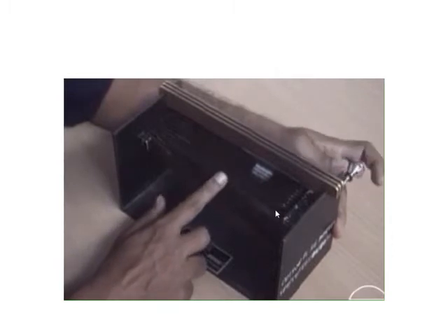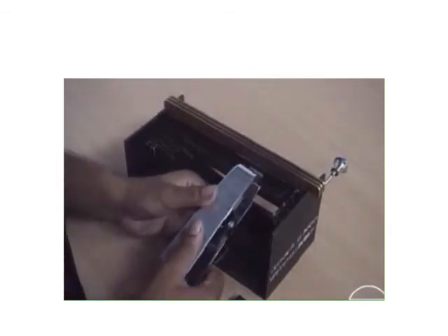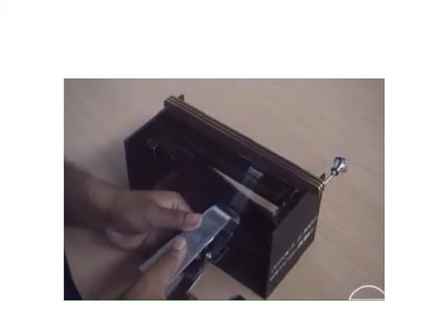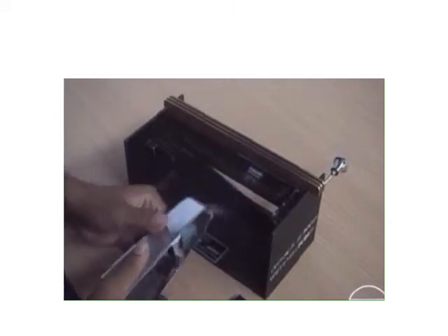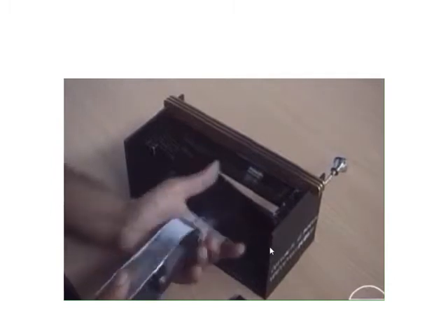See, the knob is adjusted and each bottom comb is dropped one by one, till you see the longest fiber that you have transferred. See the longest fiber, because the instrument is reversed, you will see the longest fiber first. So using tweezer, pull the fibers slowly, comb it in the needles of the bottom comb that is dropped, and next place it in the velvet pad. So the longest fiber is first placed in the velvet pad,